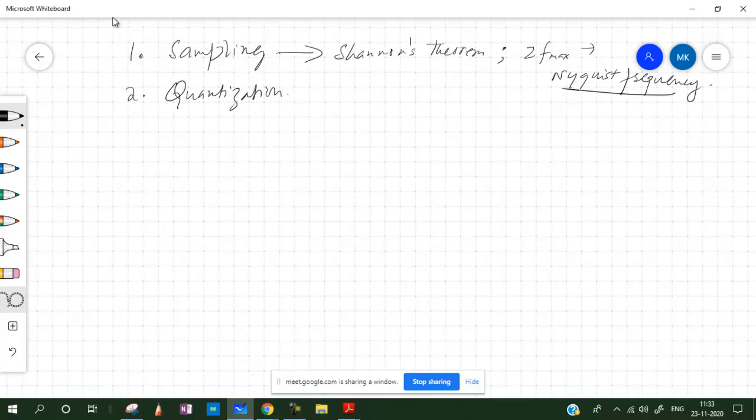All right. So for any signal that we have from any sensor, we will have to make sure that we are able to find out the maximum frequency component in that, and then use this theorem where we sample it at twice the maximum frequency component in the signal, and then we'll be able to reproduce the signal correctly. Now it's not just about sampling; it's about quantization also.